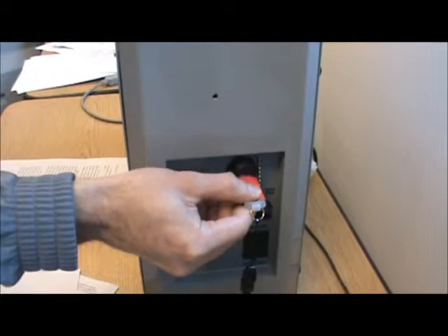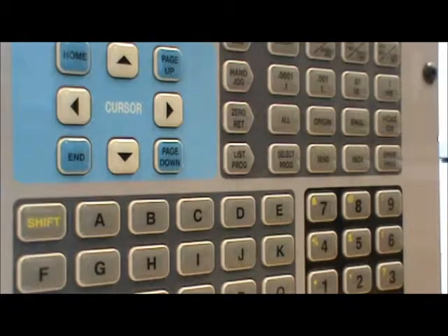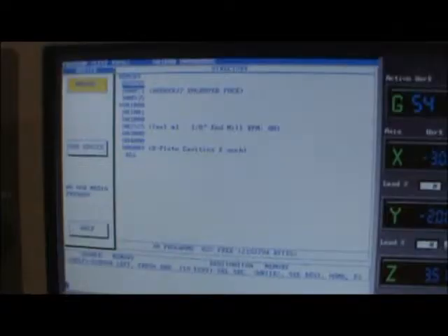Start by loading the USB drive with the desired program into the appropriate slot. Select the List Program button from the Mode section on the keypad. The left panel displays all possible devices, while the right panel displays the programs currently on that device. The left panel is active by default, as you can tell by the green border around the edge. The current device is highlighted in yellow.